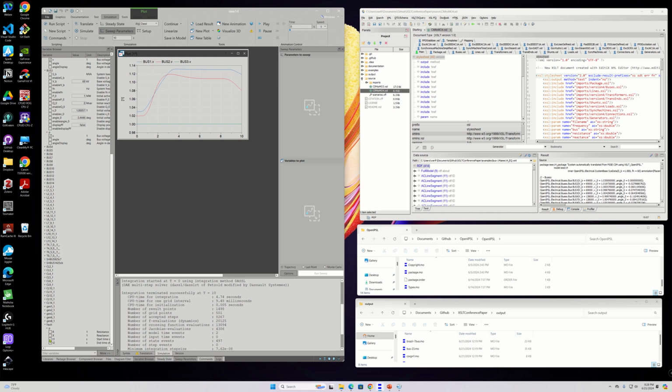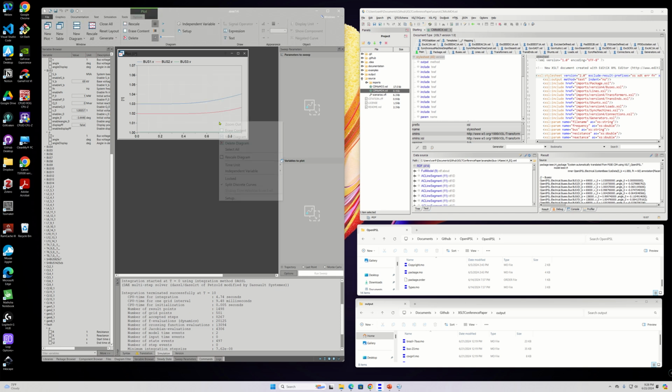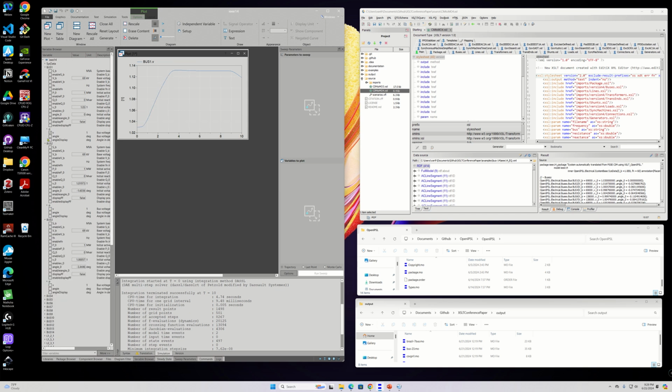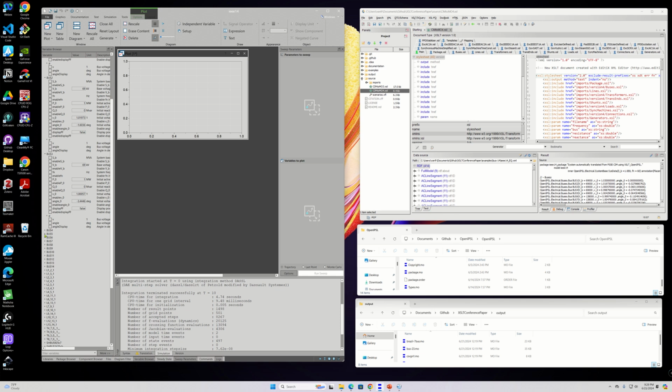You can also look at the fault block, time 1 and time 2, when they're applied. You can see the value, which is 1 and 1.01. We could see around somewhere here is where the fault is applied. So let's go look for bus number 5, where we applied the fault. Right, here you see it.